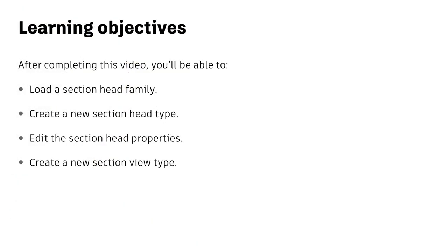In this video, you'll see how to load a section head tag into the current project, and how to create a new section head type and edit its properties, and then create a new view type based on that section head.